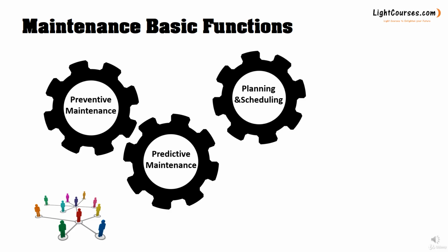And then they should take care of planning or identifying the required spare parts, if there are any required spare parts. And they have to make sure also that these spares are available in the warehouse before you decide to execute the job. They should also plan the needed manpower, the needed skills and competency to do the job. They're supposed to plan for the tools that are needed to execute the job. They're supposed to be in charge of planning the special equipment in case you need a crane or a forklift. All these special equipments they have to plan for.